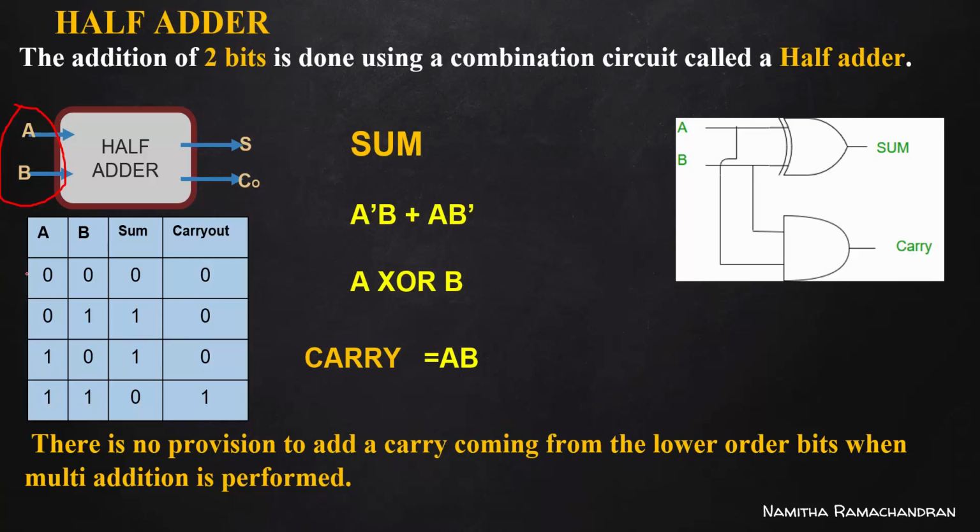These are actually equivalent to our decimal numbers from 0 to 3. Okay, so here it is, considering this half adder circuit performing the addition of 2 different bits, A plus B. First case is 0, 0. So by adding 0, 0, this is A, this is B, 0 plus 0 is 0.